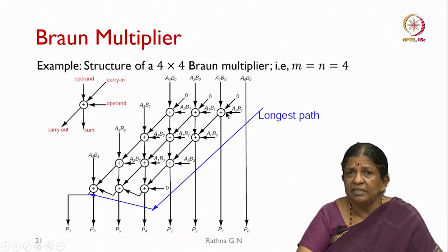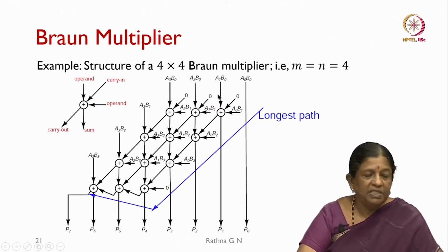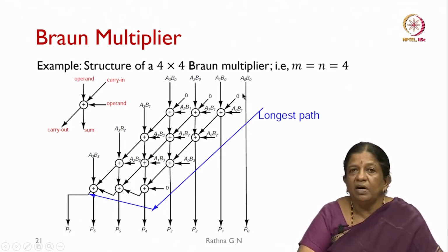These are the adders. As you can see, this is the multiplier we are representing, but we need AND gates to do the multiplication of these numbers. That is the additional hardware it requires. In the first stage, no carry in is going to be there, so we are using all full adders. That is why the carry in is going to be 0 in this case.